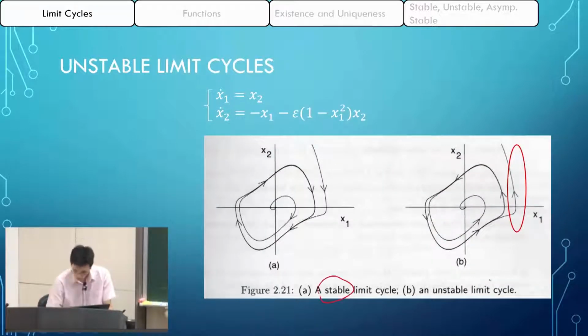Now, what is unstable? This is unstable on the right-hand side. For example, if your initial condition is here, it can go outwards and diverge, right? So it's unstable, even though if you start from inside, it might converge to the origin. From some other location, it can go unstable. So you cannot say it's stable. You can only conclude it's unstable. Stable means no matter where you are, you should guarantee that it will be stable. We will review the definition of stable later.